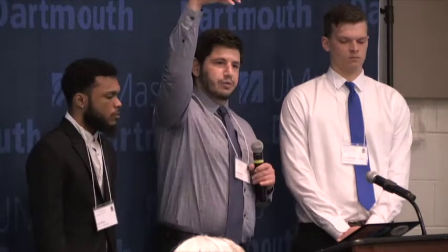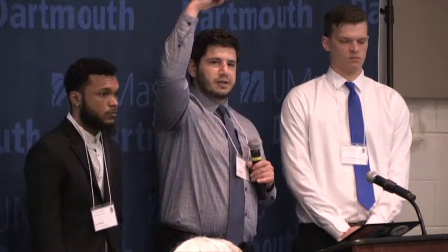Thank you. So 2D location can be found using cell tower triangulation or GPS. We needed to get the 3rd dimension, and that was really our task. At first we were thinking of using RF antennas to transmit and receive signals to phones, possibly mounting 3 on the ground around the building, and then flying a drone with 1 on top to give us signal diversity and try to triangulate ourselves. But our biggest obstacle was multipath propagation and cell identity.